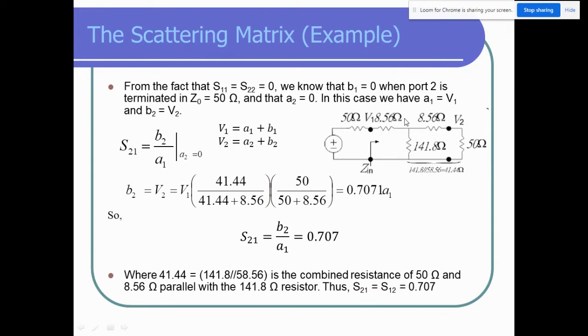But this voltage will distribute in here and everywhere, isn't it? So in terms of V1 we will find out V2. However, we need to bring what the voltage here is first in terms of V2. So to do that, we need to find the total resistance of this network.